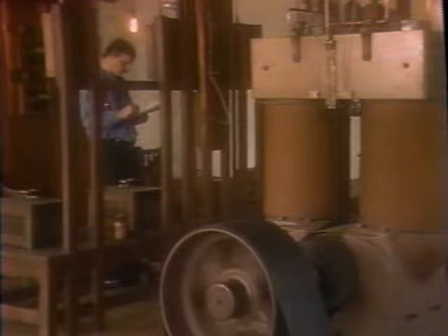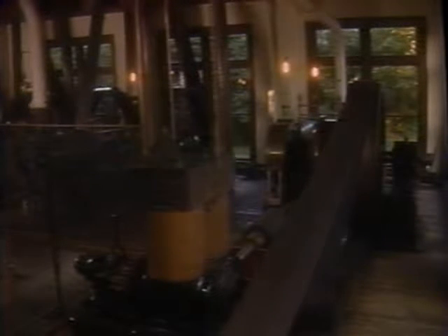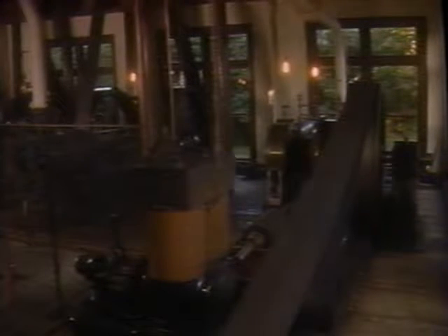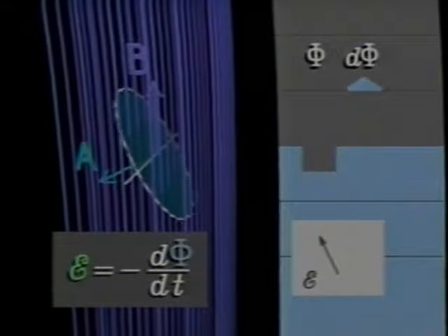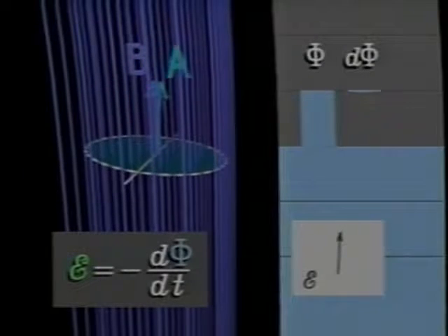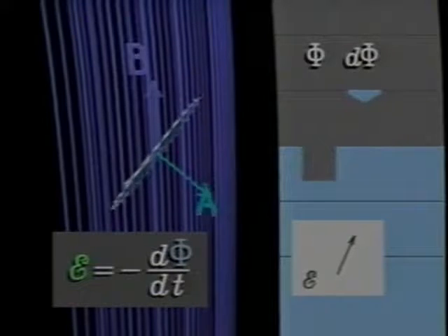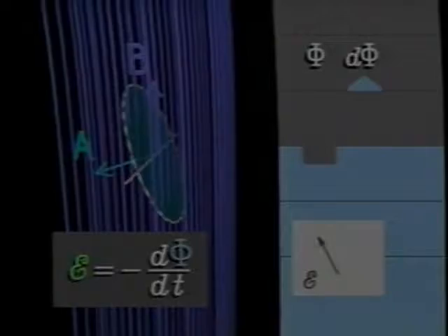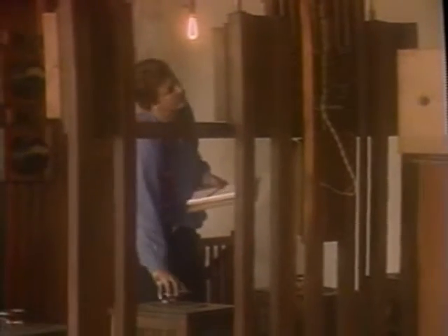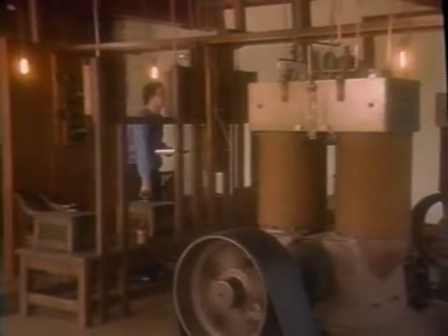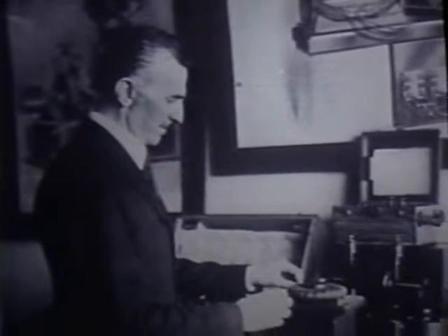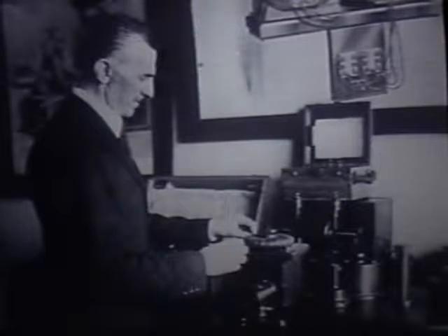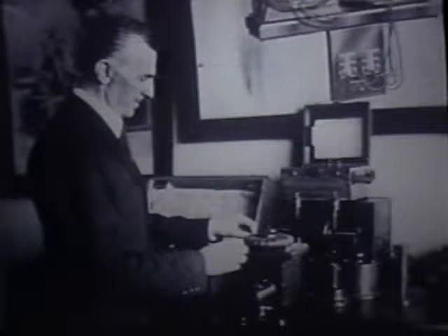And no matter the engineering shape they'd take, the principle of every dynamo would come from Faraday's law of electromagnetic induction. Rotating a loop of wire in a constant magnetic field continually changes the flux through the loop. The resulting voltage and current are sinusoidal, going first one way, then the other. Using elaborate sliding contacts attached to the rotating coils, Edison was able to compensate for the oscillating voltage, drawing current that always ran in the same direction from his generators. Tesla thought Edison's system of direct current was costly and inefficient, and that alternating current would do the job better.